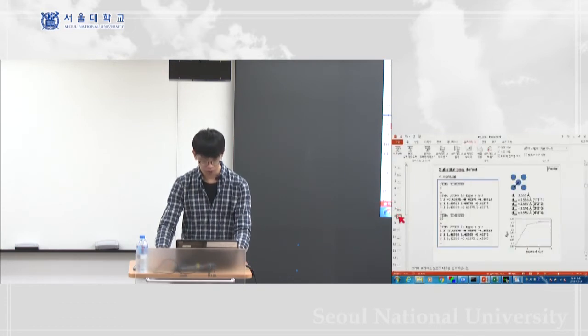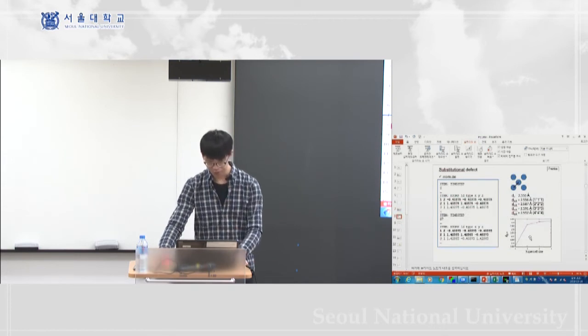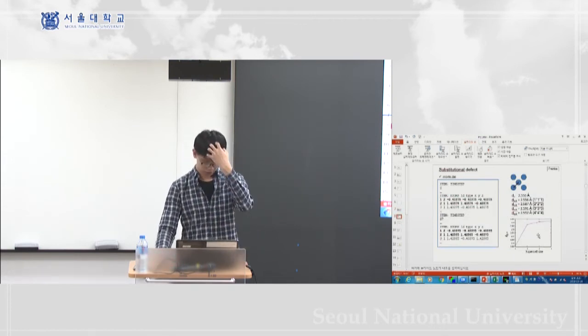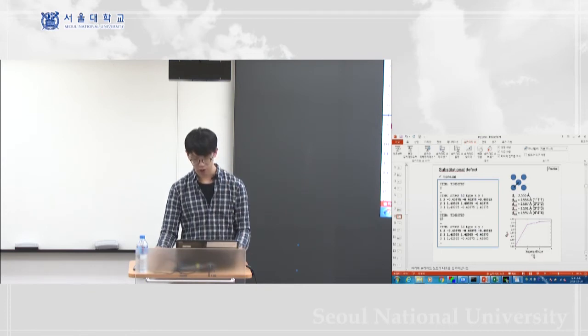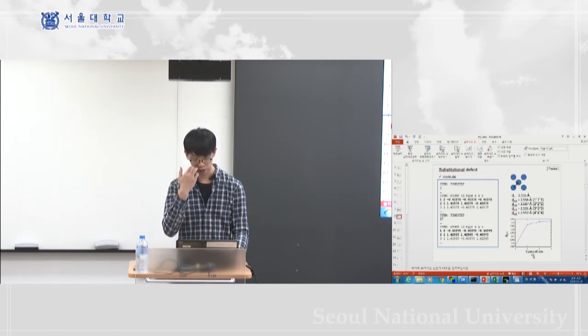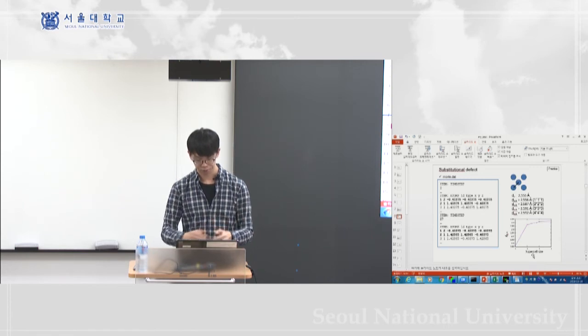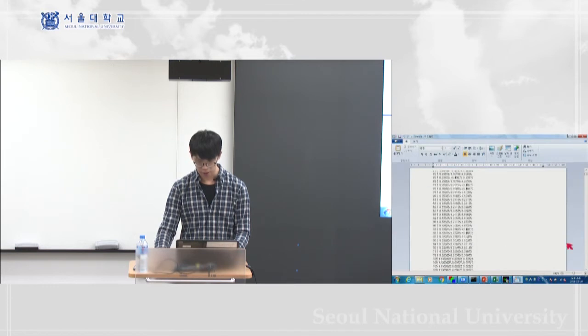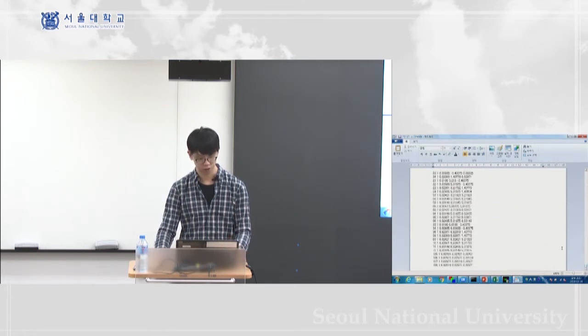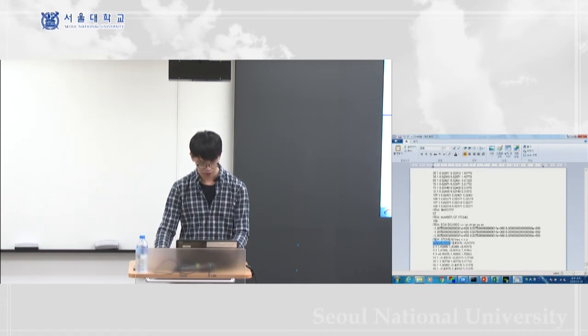What we are trying to do is a supercell test to see how large the supercell needs to be for the copper-aluminum distance to converge. At the last line, after all the relaxation is done, there's going to be this line. The first atom is aluminum and the second atom is copper.